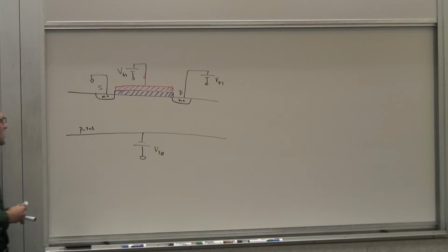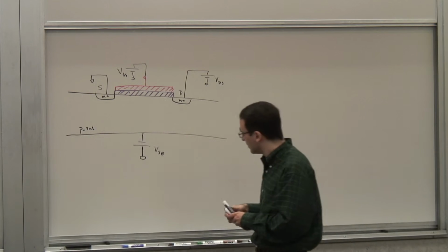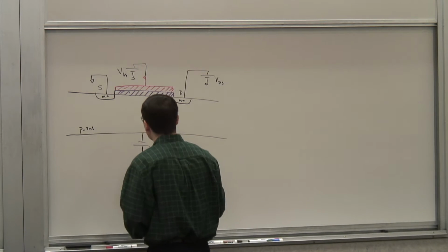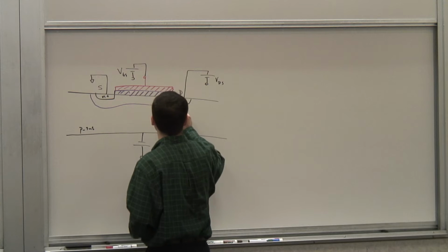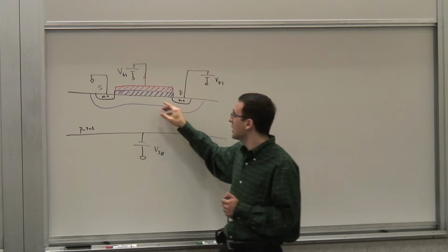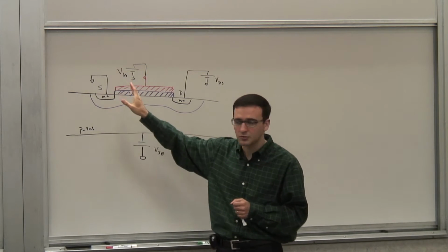And then of course what we saw is that at lower voltage, in general, to determine what the threshold voltage is, you have to take into account the effect of this depletion region underneath. You have this depletion region. Part of it is formed by these junctions, but the rest of it has to be formed through the application of this gate voltage.